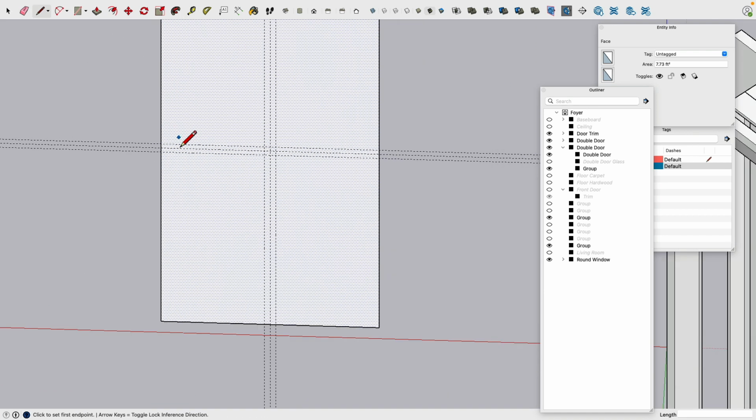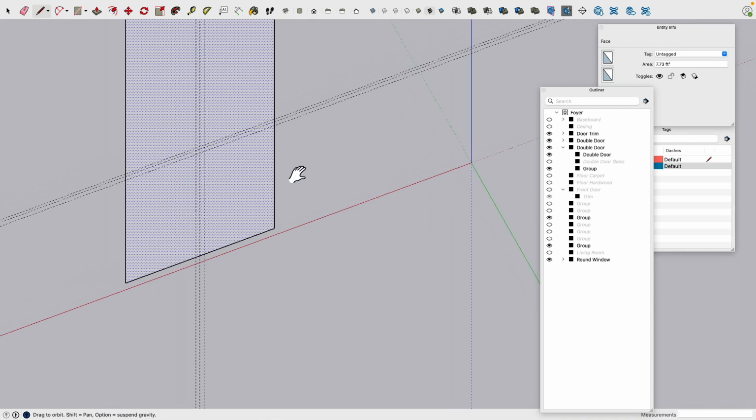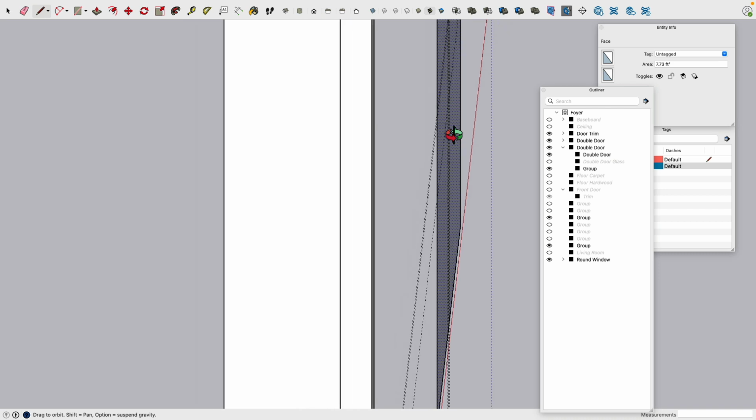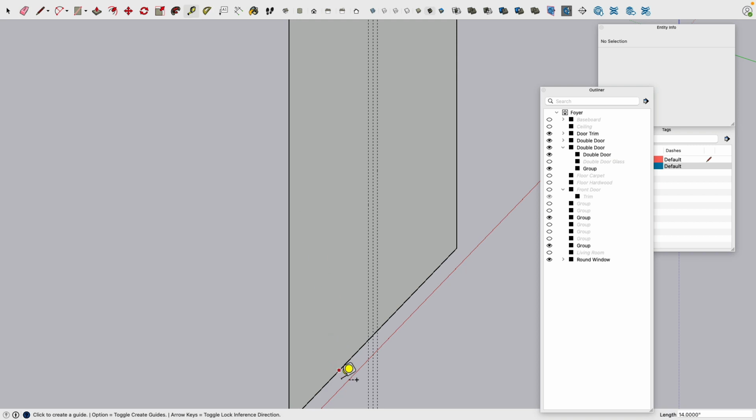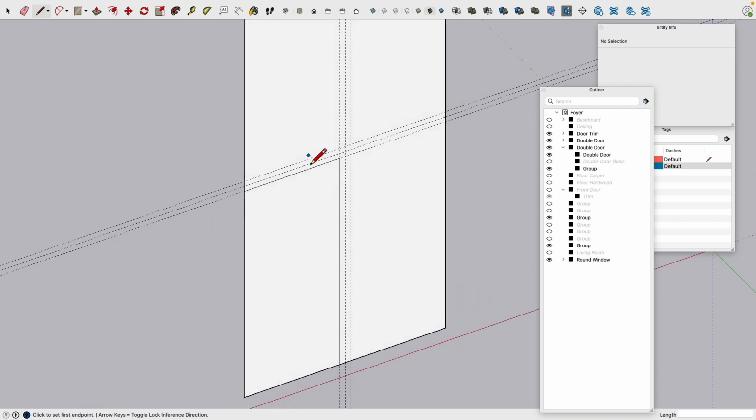So here's actually the little pattern trick we're going to do, as long as everything here works out, which it does not. There are some lines which are incorrect. Okay, so one more time along the z-axis, 15.9 along the z-axis, 0.375, same here again, 0.375. Good. Yes, that's the way this is supposed to work.